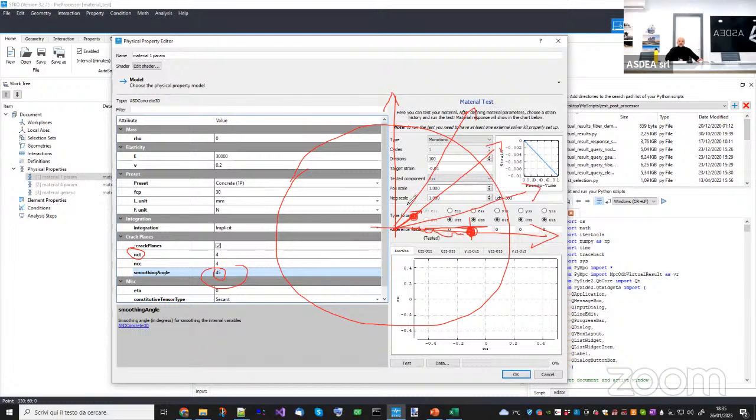It means that if I flatten this on an XY plot, and here I have the damage, for example, and here I have the angle, and this point here is at an angle of 0 and I reach a damage of 1, in the other vectors I will not get 0, but I will smooth them using a Bell function, okay? So this is basically used to smooth the damage in the immediate neighboring of a crack.